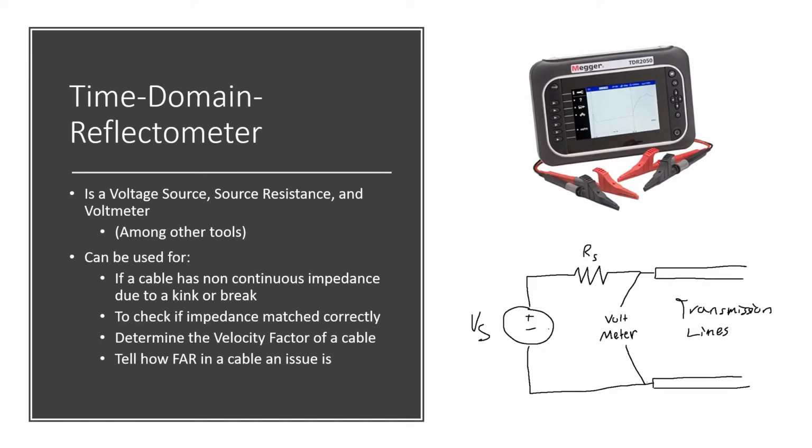Now finally on to what a TDR is. A TDR will commonly resemble the image in the top right. It usually has a screen, buttons, and to be honest, might just resemble a fancier multimeter or some kind of handheld oscilloscope. But what it does is very different. Its primary feature is that it can read waveforms on the nanosecond or smaller scale. And this is to accommodate the fact that circuits might reach steady state extremely quickly, and you want to see how it got to steady state.